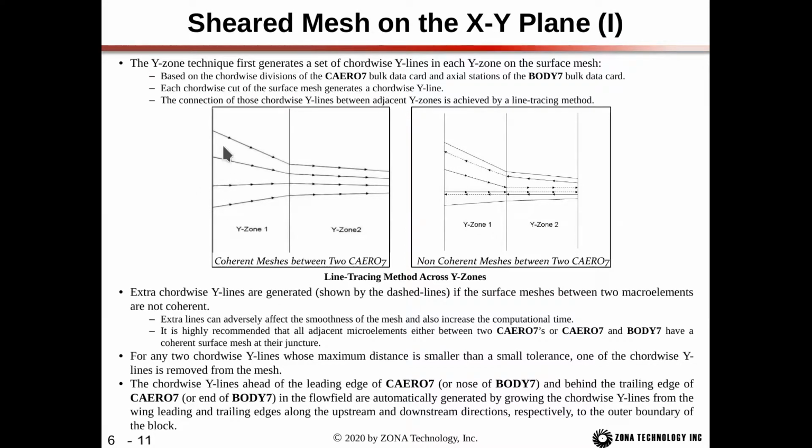It's just that the extra cuts in the wing will go ahead and cut through the body. And so I'll still have the 40 volume boxes along the fuselage, but then when I interpolate the flow solution back onto the surface panel model, those 4 boxes will get mapped back to 1 surface panel box.